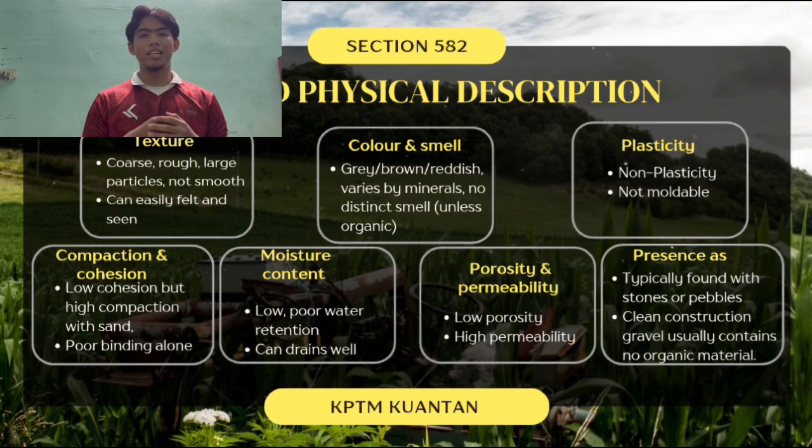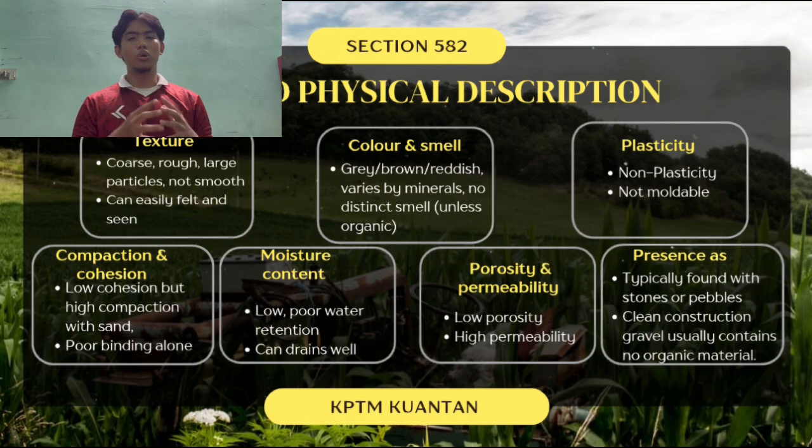And then for the plasticity, the gravel is non-plastic and not moldable. And then the compaction and cohesion. The compaction is very high if the gravel comes with sand, but there is no cohesion. And then the moisture content. The gravel has very low and poor water retention.